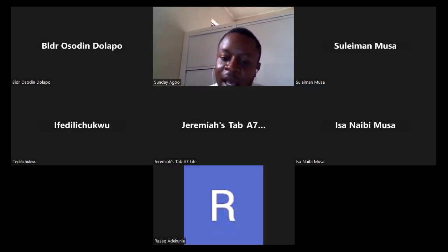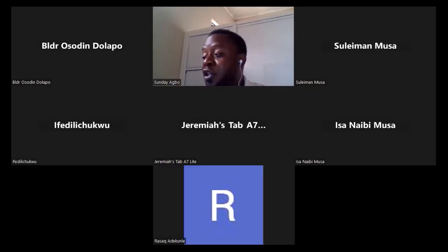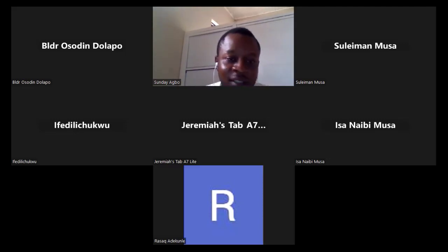This is one of the important uses of the coordinate reference system. And at the same time, in the coordinate reference system, we have what we call on-the-fly projection. Fly, F-L-Y. What it means is the ability for you to use WGS. When I say WGS, that is the World Geodetic coordinate system. Anywhere you are in the world, you can use it, just that the level of accuracy is not as high as the projected coordinate system.